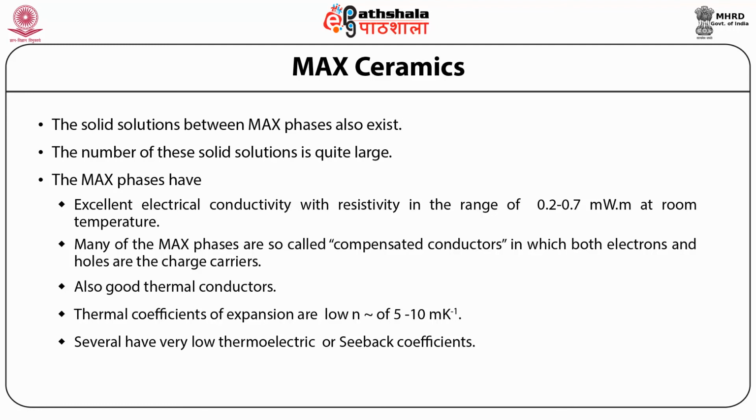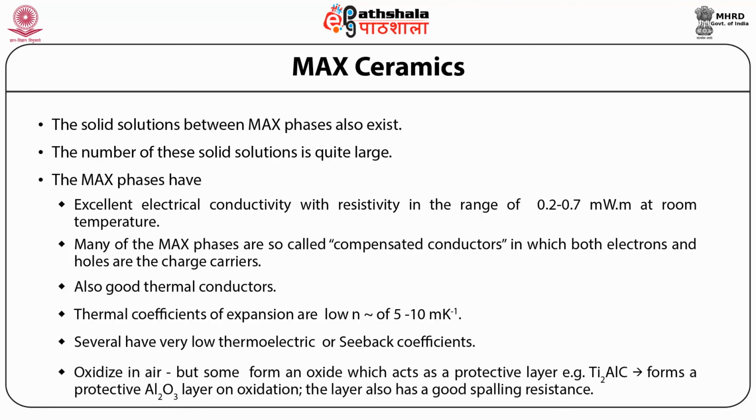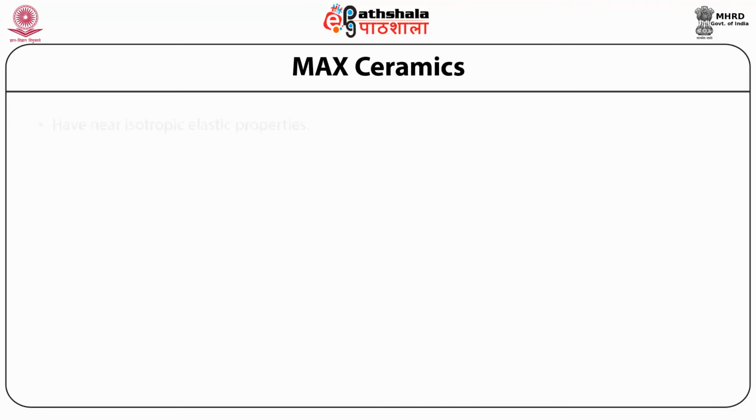The MAX phases oxidize in air, but some of them form a protective oxide layer, making them resistant to oxidation. For example, Ti2AlC forms a protective layer of Al2O3 on oxidation. This layer also has good spalling resistance, making this material quite resistant to oxidation. The MAX ceramics have near isotropic elastic properties.